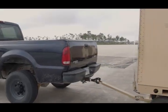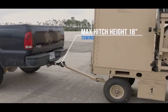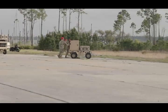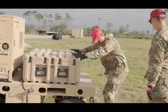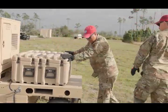and keep the maximum hitch height at 18 inches. When positioning trailers, use manual methods only. Do not use the truck to back in or park trailers into their final positions.